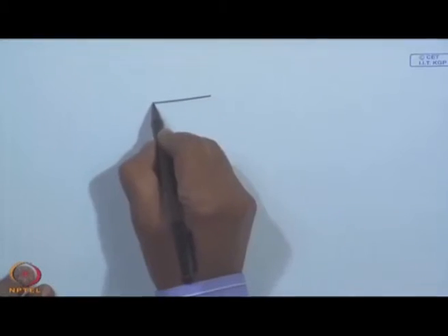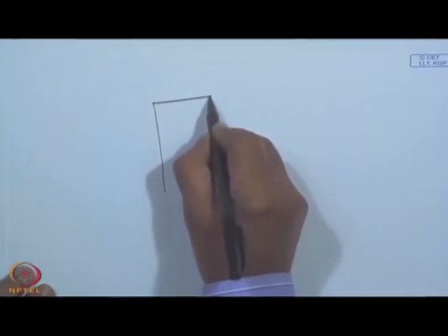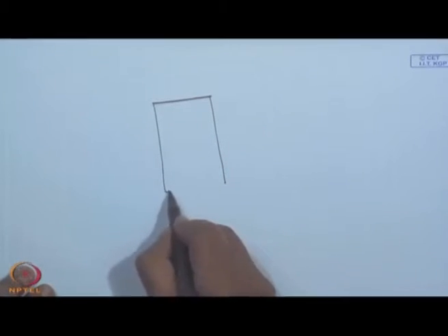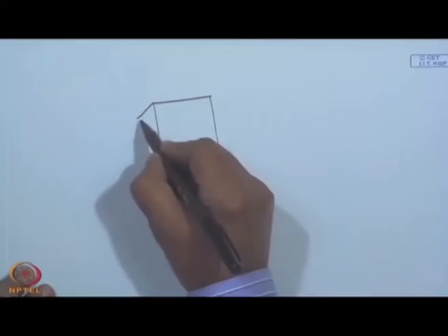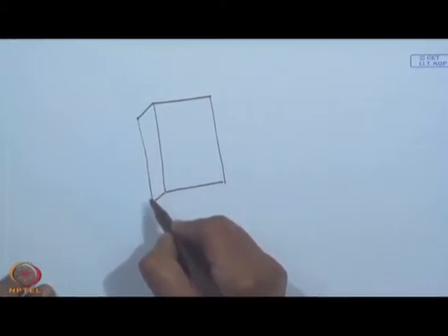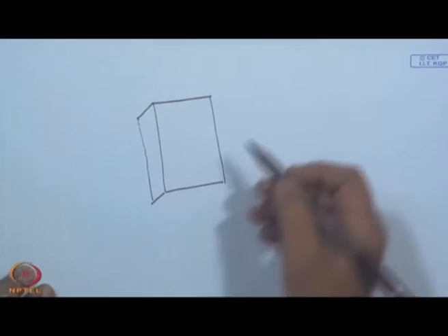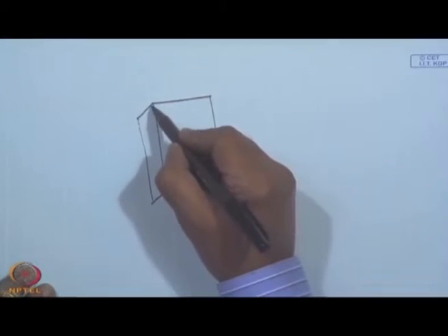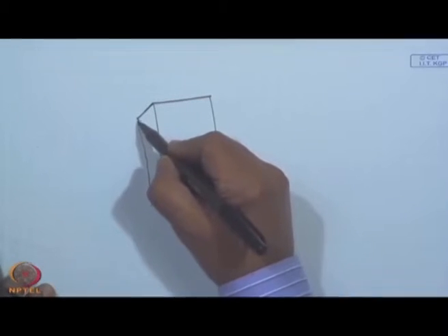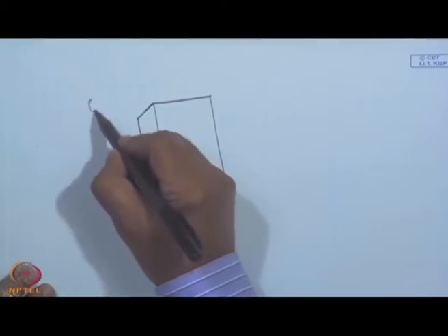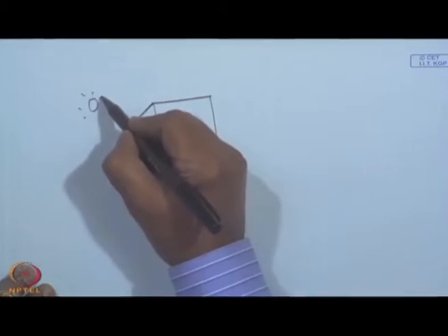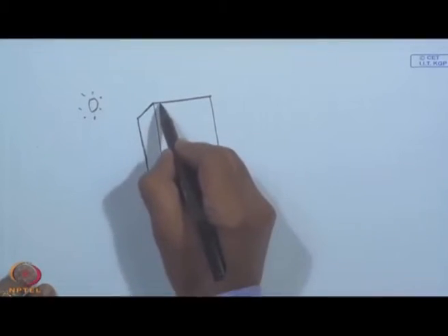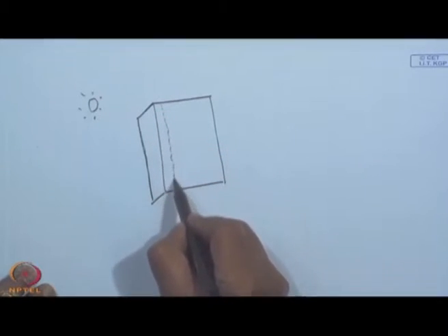Incidentally, a wing wall is something like this, which we have of course dealt in detail in the lectures. I will show only one. If you see some of the buildings, there will be a vertical, or it looks like it is. This is the wing wall, and depending upon if the sun is on this side, like if this is south, this may be west, this will cast a shadow here.